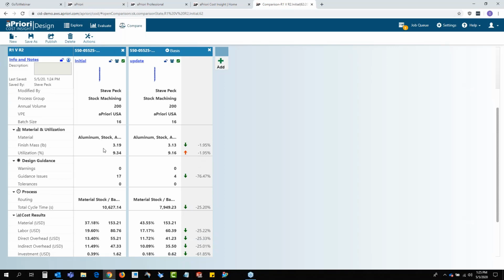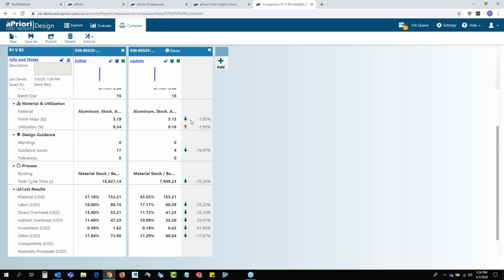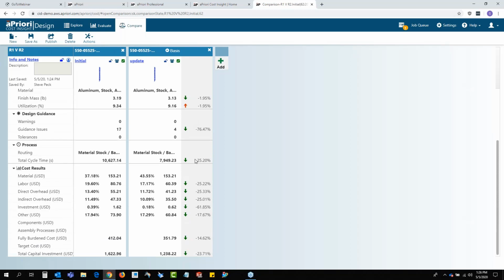So one important piece, this is an airframe component, a frame. Obviously, weight is critical. I've moved in the right direction there by modifying the radius at the bottom of all those edges there of the flange. I've actually reduced the radius, removed a little bit of material, still structurally acceptable, but this is kind of an added bonus of pulling a couple % out of the weight of the part.